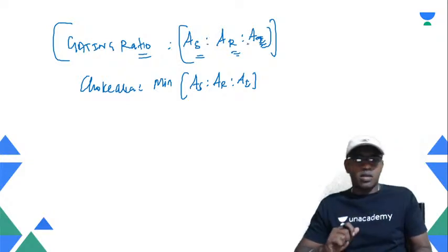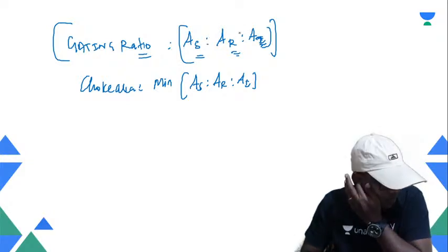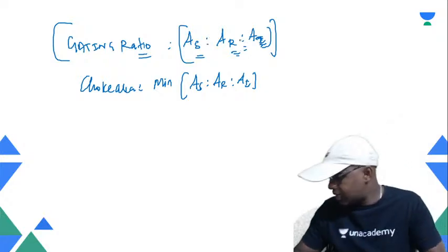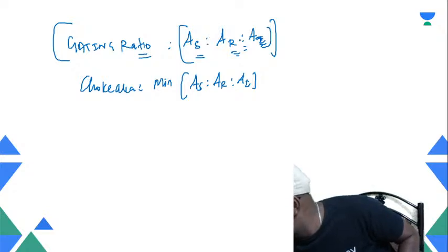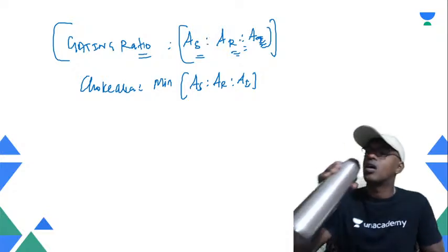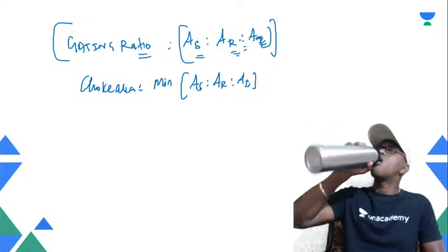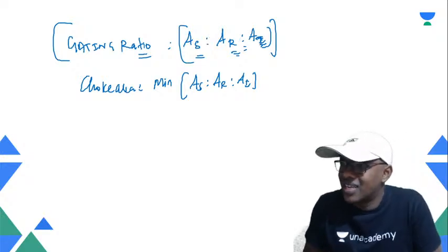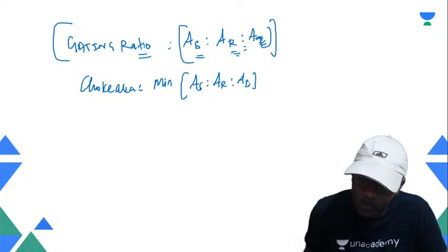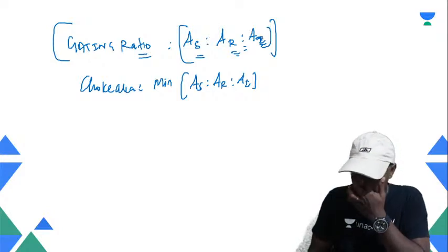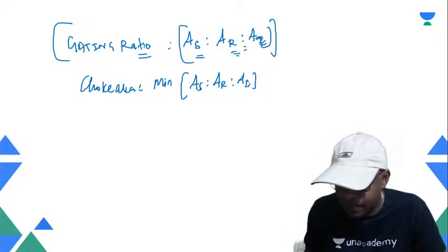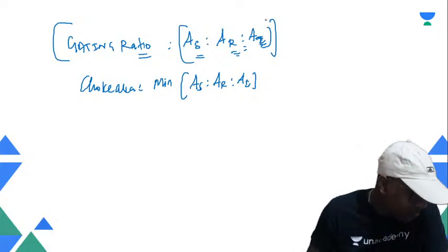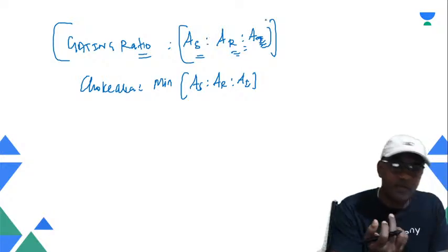Okay, great. So these are the terms I have to convey. So now let's move on to the classification of the gating system. Sir, classification of the gating system can be many types, right? It can be many types. But we are talking particularly about the two. It is all about the pressure above the molten metal in the pouring basin. Is it pressurized or non-pressurized? I'm also talking about the position of the ingate: top, bottom, parting or step. So these are the major classifications, guys. Kindly make a note. Okay, let's move on.